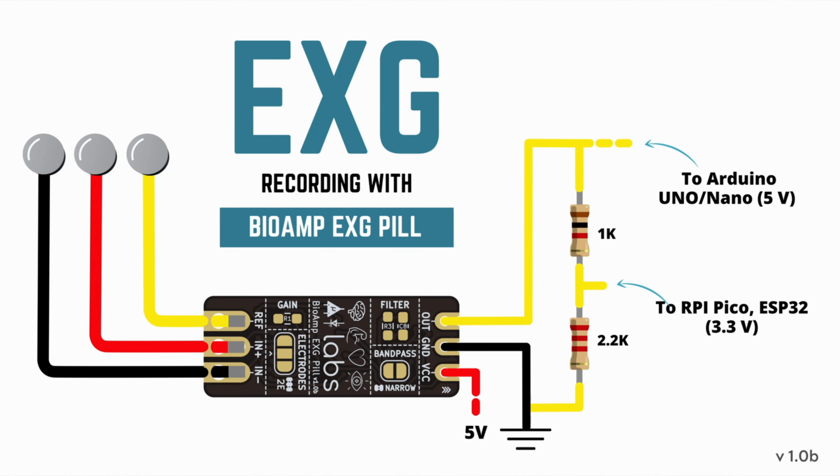Before we move on to coding, I'd like to point out that boards like ESP32 or Raspberry Pi Pico need to be connected like this, through a voltage divider because they operate at 3.3 volts.